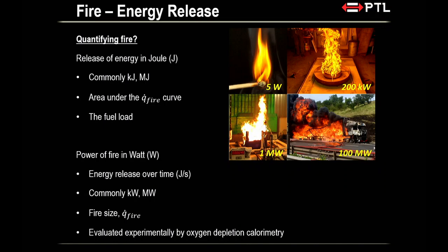So how do we quantify fire? Again, a little bit of basis, right? So we quantify energy release in joules. More commonly, we will refer to kilojoules or megajoules. You will see these units come about throughout our discussion. It's a little bit like force, structural engineers deal with kilonewton, megapascal, that sort of stuff. Now, the area underneath the curve that you see before, if you integrate all that area, that will give you the total energy release during that fire.